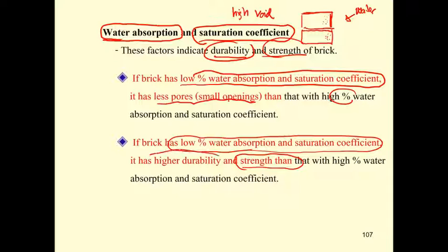And for durability, I'm talking about the freezing effects on the water inside the brick, and if the brick is subjected to the sunshine, that water will change status, which is also going to decay the brick. If the water freezes, the volume of the ice expands, and that's going to put pressure on the brick and lower the durability of the brick.